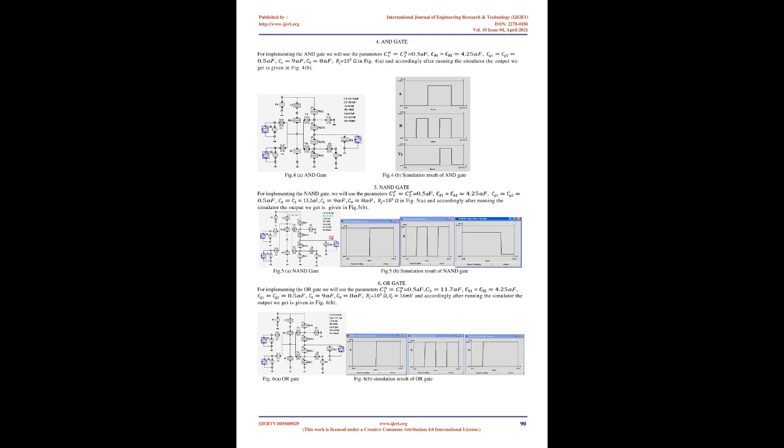The operation of the inverter will be like this: the output V_0 value will be high when the input voltage V_in is low, and V_0 value will be low when the input voltage is high. For achieving this target, we set the voltages V_b1 equals 0, V_b2 equals 16 mV along with the tuning gate voltages, at present V_in, both for SET 1 and SET 2. Now if V_in is low, SET 1 is in conduction mode and SET 2 is in Coulomb blockade. This effectively results in the output being pulled to the bias voltage, and causes the output voltage to be high.